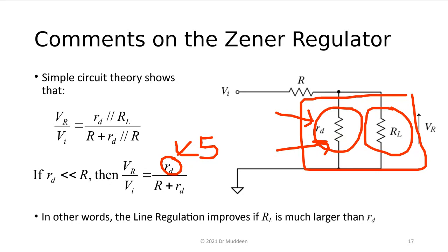Many times you would find that students would come into the lab, design a circuit, implement it, and then when they hook up the power supply to the circuit, nothing works. Your automatic belief is that something was wrong with the circuit. One of the first things you check when things don't work is to go back to the power supply.